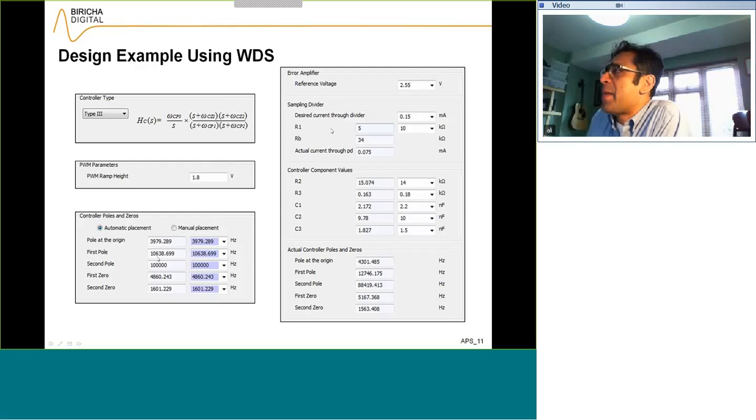And then on the next tab, you have got the reference voltage. Again, this is user-defined and is based on your chip, and the potential divider that goes into the analog IC. That one is decided based on the user's requirements of how much current you're willing to pass through these two potential divider resistors. And of course, you decide that based on how much power loss you're willing to have. Somewhere around 60 milliwatts is something that I'll be happy with in a 0805 or, let's say, 1206 package.